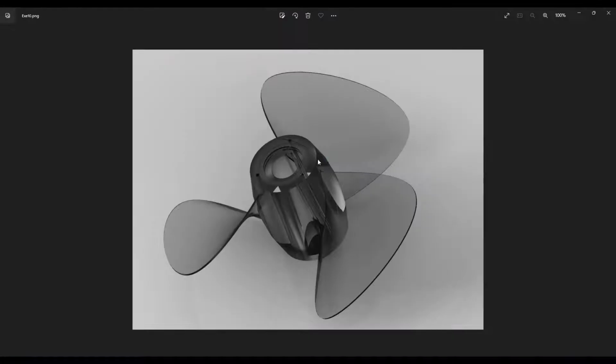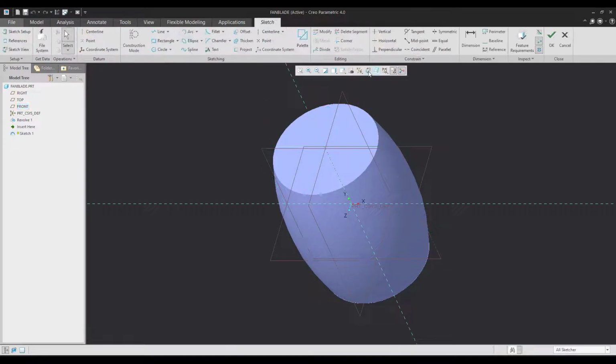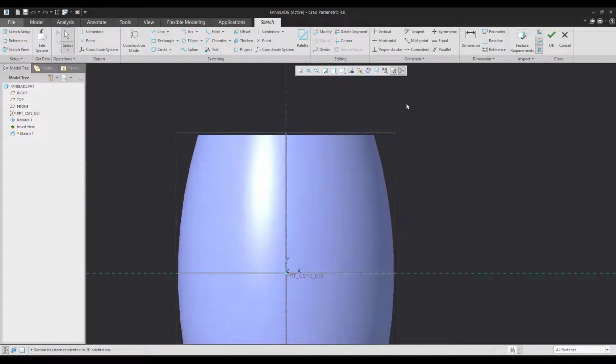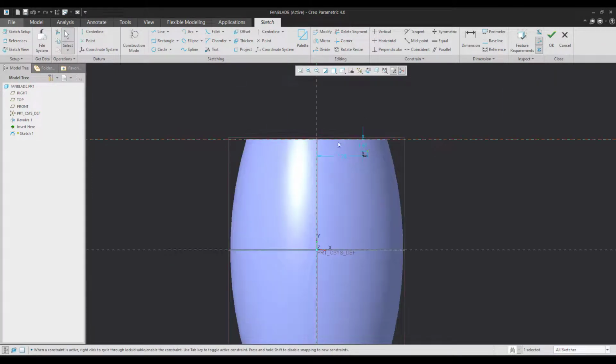Now to create this blade, I would require to use 3D points as well as 3D curves. So let me begin with trying to make the start as well as the end point of the curve. So on the front plane, I would like to create a point since I know where the blade is coming, since I know where the blade is starting from. Let us assume that the blade starts from 2 mm, which at a distance of maybe around 8.5.